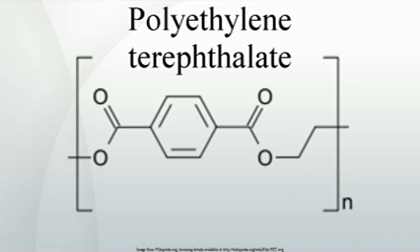When recycling polyethylene terephthalate, or PET, or polyester, in general two ways have to be differentiated. The chemical recycling back to the initial raw materials purified terephthalic acid, PTA, or dimethyl terephthalate, DMT, and ethylene glycol, e.g., where the polymer structure is destroyed completely, or in process intermediates like bis(2-hydroxyethyl) terephthalate; and the mechanical recycling where the original polymer properties are being maintained or reconstituted.